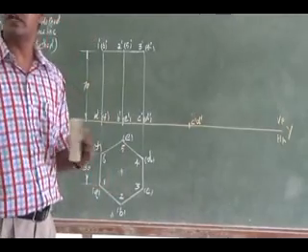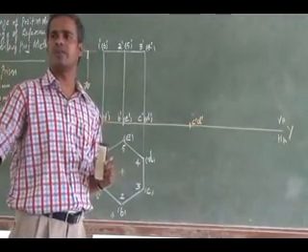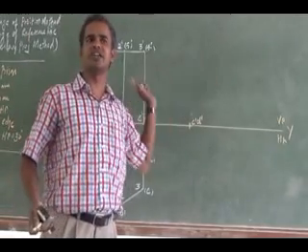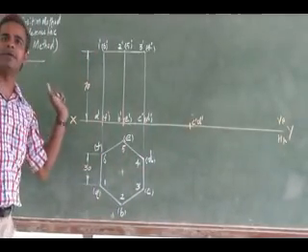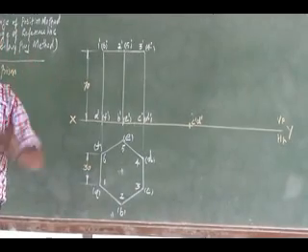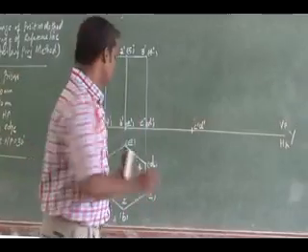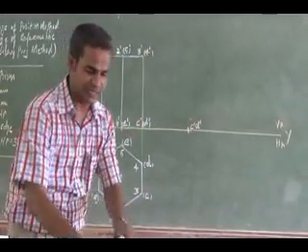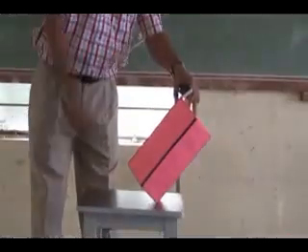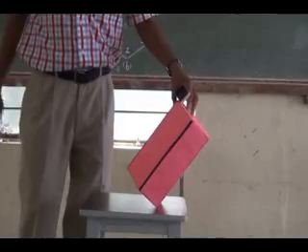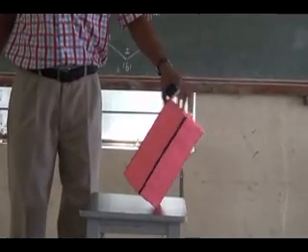Okay, for your easiness in projection of pyramids also, what you can do, the axis inclination, you convert it as a base inclination. So what is the axis inclination here? It is 30 degree. So if I tilt this solid to 30 degree, axis 30 degree inclined to HP, what about the inclination of the base to HP?